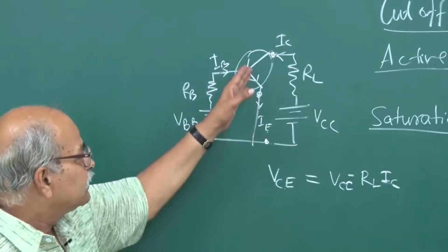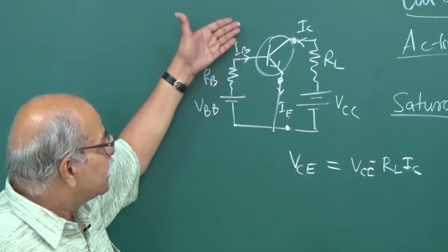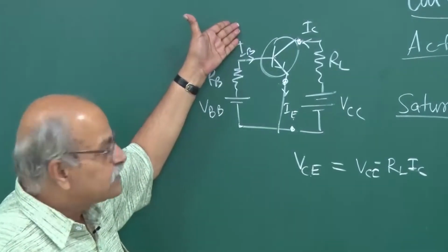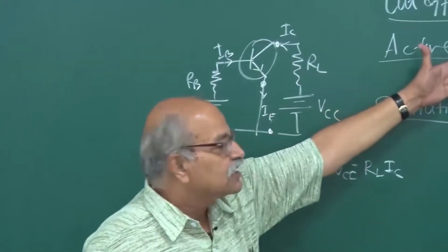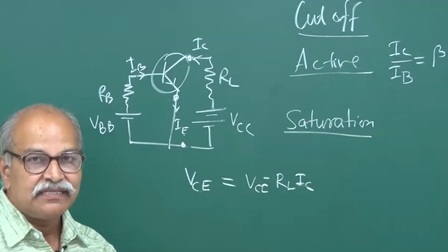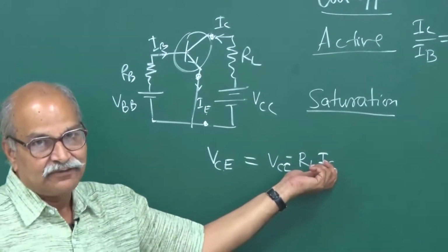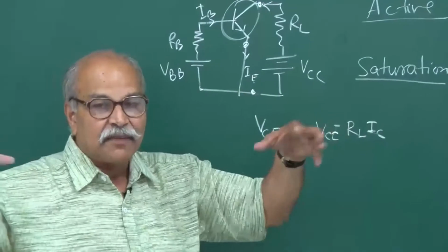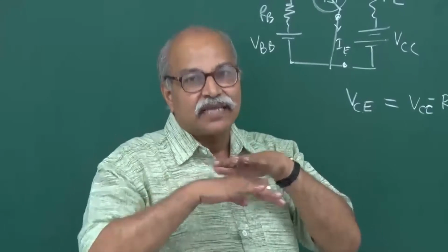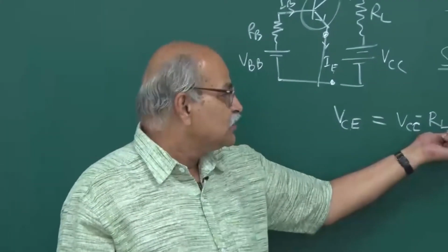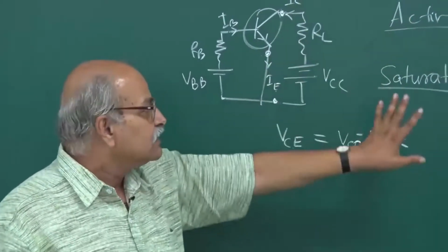So now we say that it has reached the saturation stage, and if you increase this IB further, since it is no more sufficiently reverse biased, it will not follow this equation, it will not draw that much current, and it will almost be constant at its maximum value. So it has saturated. The capability of drawing the electrons from this base is saturated, and therefore this current is no more increasing. Even if you are increasing IB, this is not increasing. So that is the saturation region.